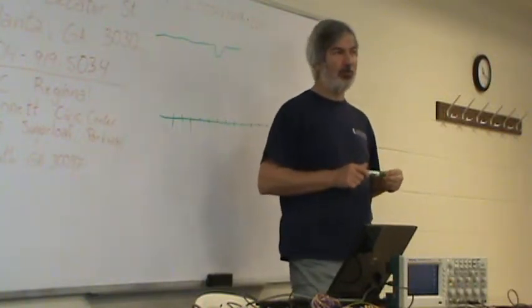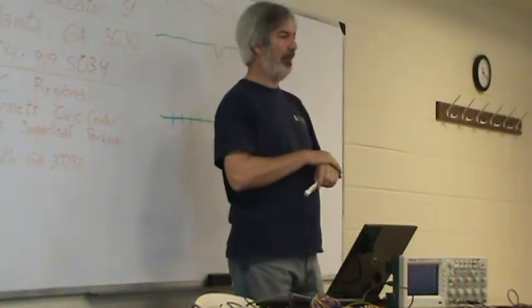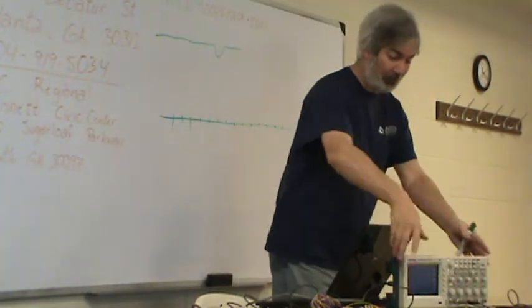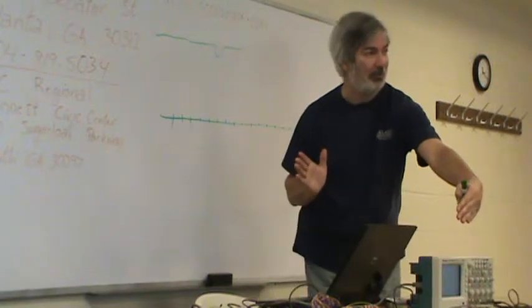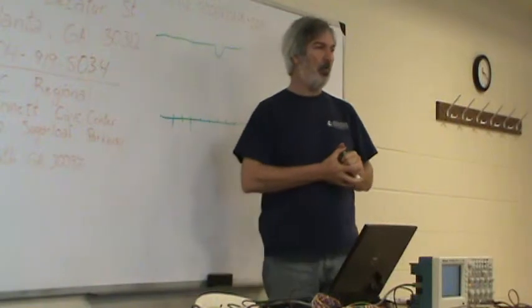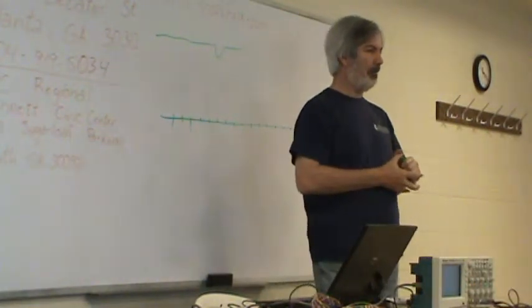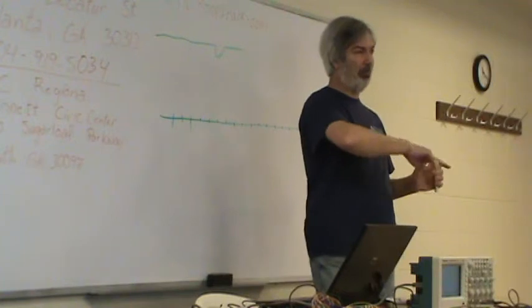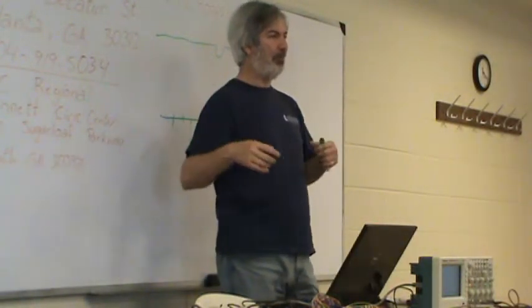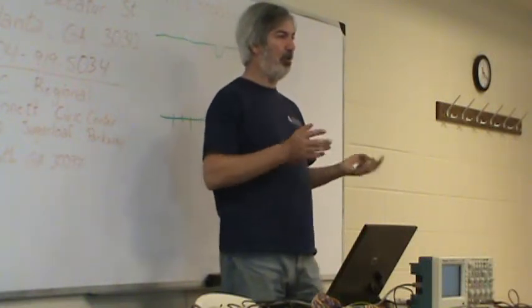With digital scopes, as opposed to the older fashioned purely analog scopes, which typically are tube type scopes, you usually have a scope that's about this big, except it's about this deep. It's actually got a tube in it. When you're dealing with fast signals with a tube scope, you see an actual completely honest analog signal. So you very seldom have problems with the scope telling you one thing when really it's something else.